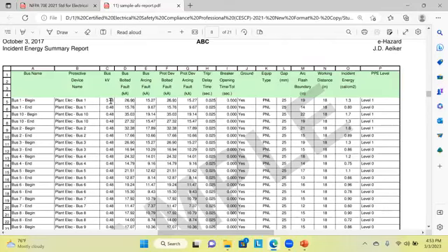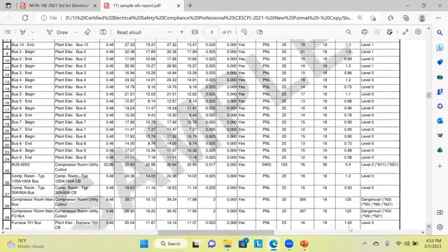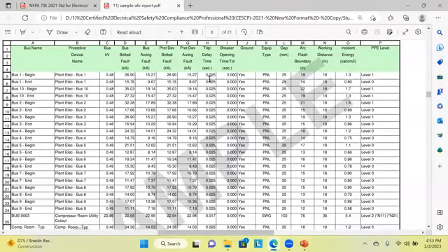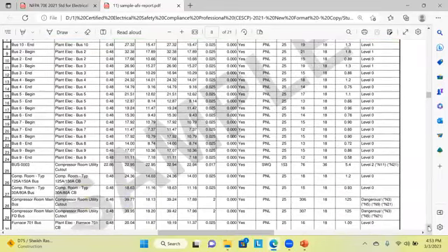On the same voltage level of 480 volts, if we go down for the same organization, here the device clearance time is in milliseconds, around 25 milliseconds or 0.025 seconds. If the device clearance time is 2 seconds for the same voltage level, the incident energy is 125 calories per centimeter square at the LV side, low voltage side. So if this type of report comes to you and you analyze it with your consultant, you will definitely ask why this incident energy is so dangerous.